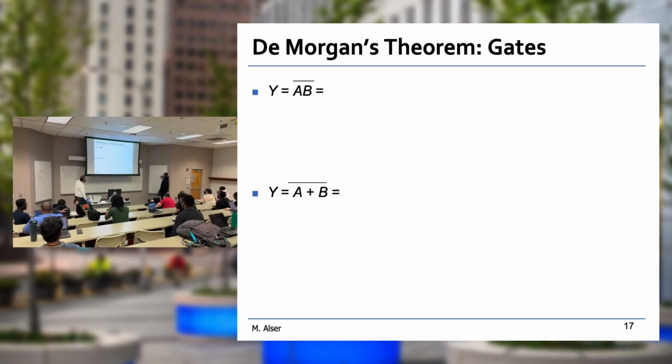So we have A plus B all to the bar. Excellent. You split it into two sides, and you flip the sign. You distributed the bar over the two sides. Excellent. Done. You're done. Now you need to draw it. You need to design the circuit. Wait a minute. Which equation are you implementing? Second one. Do we have OR? We don't have OR. So AND is like a half circle.